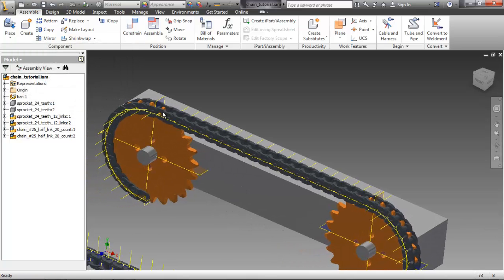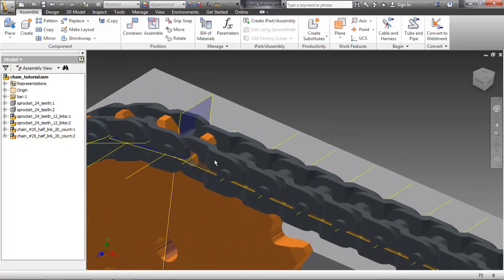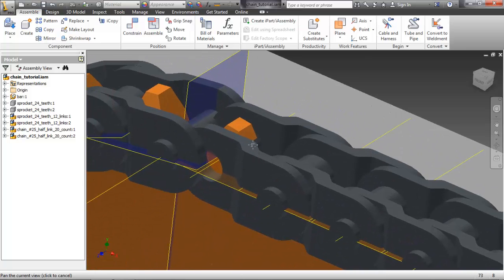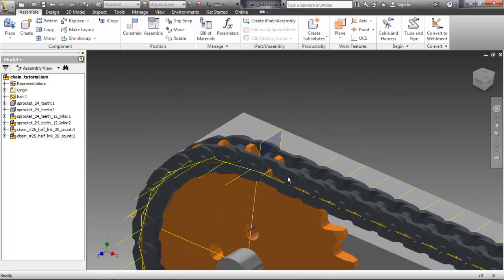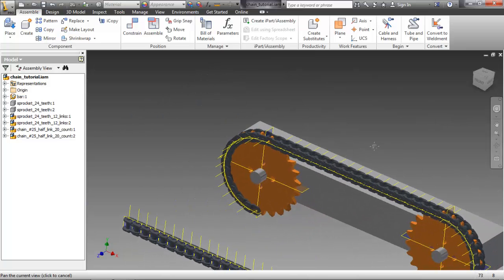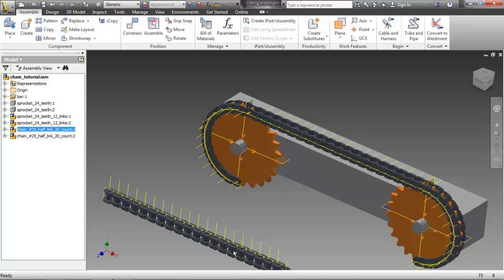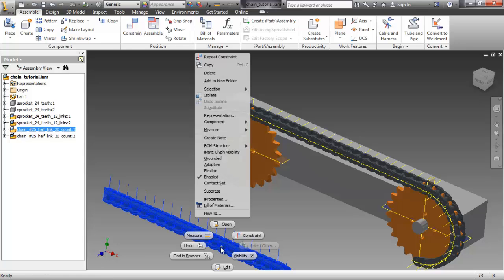And if you zoom into the other side, you can see why we place the axles 5 1/8 inches apart. This should be the worst case scenario. There are 2 ways to fix this problem. One way is to move the axles closer together, but in many models this is not possible.